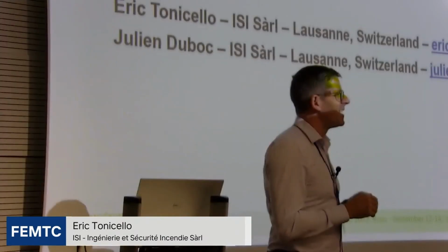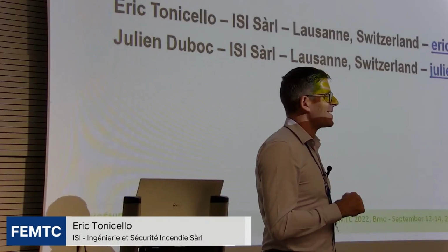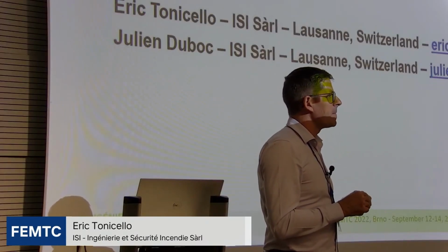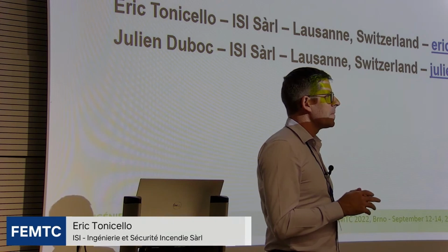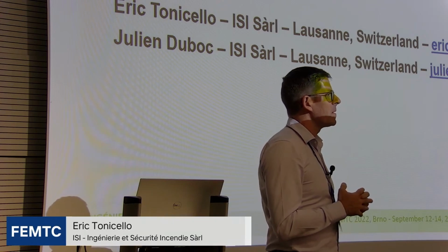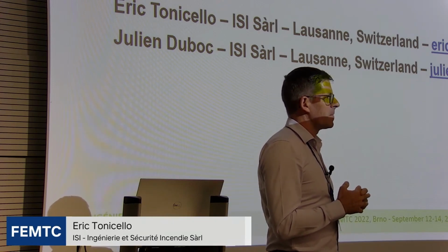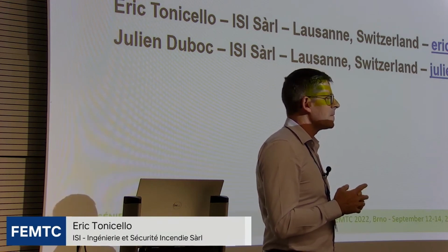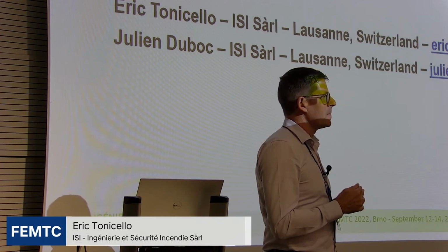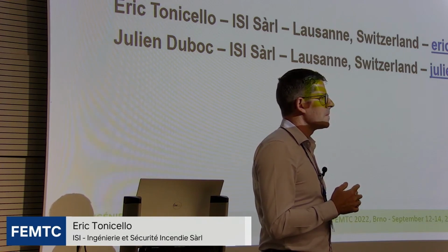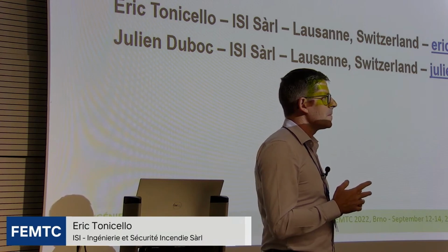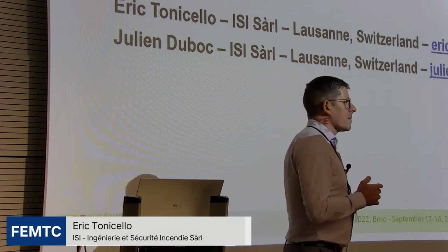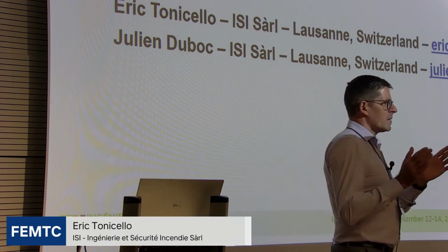I know nothing about pre-stressed concrete, but regarding the evacuation and the time that is left for evacuation in tunnels, when you use water mist, the smoke stratification might be a problem with the egress. Have you considered checking a sweet spot, leaving a gap between the operation of the nozzles to allow for egress?